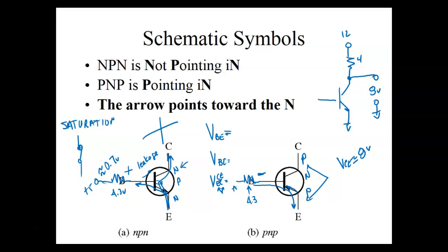So we use these things all the time to control things. I can come over here and touch a little tiny button on my car and crank my car, right? Well, I've got to get some type of current gain out of something. We're acting like open switches and closed switches. So with a transistor, I can take a very small base current to control a lot of emitter to collector current. It allows me to touch something and control a lot of current, or bring in something that's got an antenna sticking up.